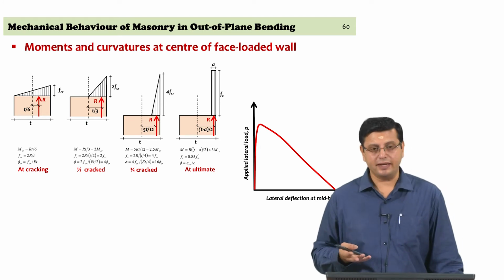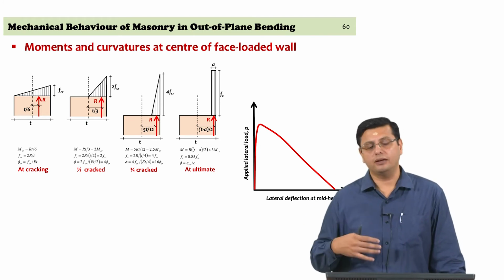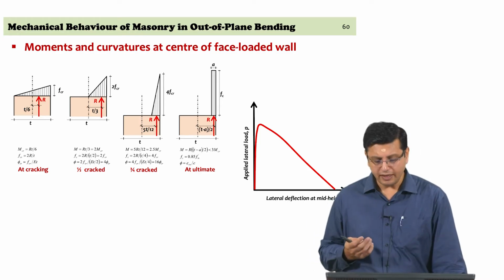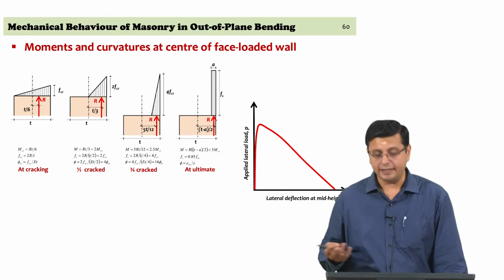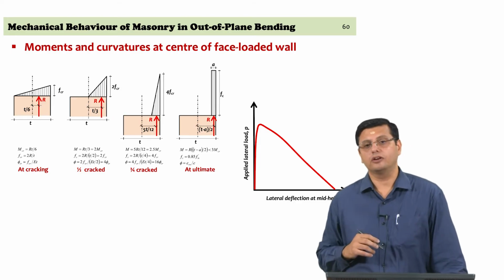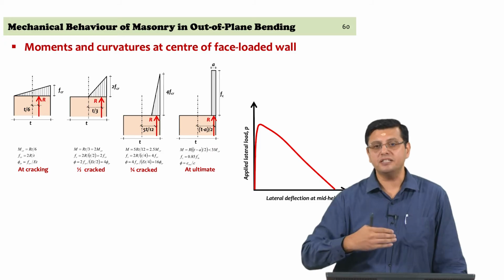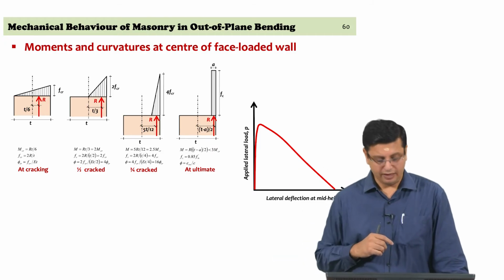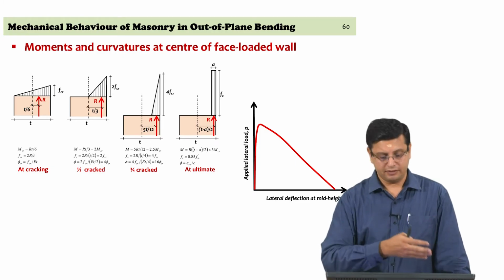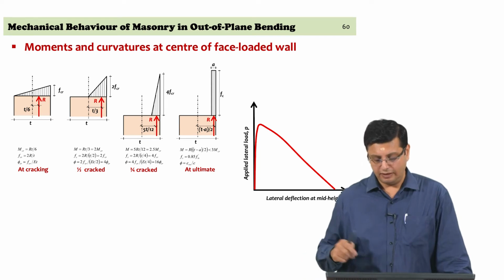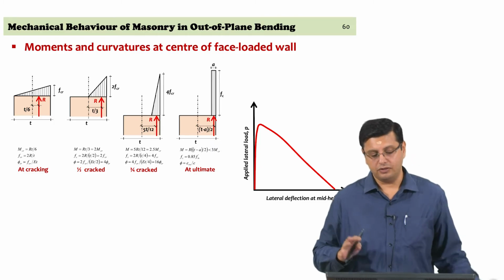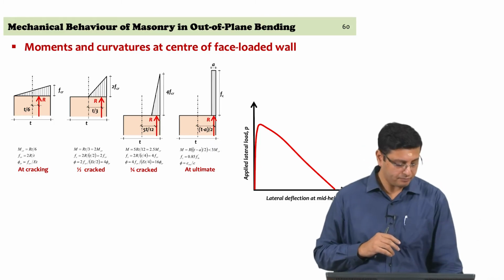In this particular approach, we had looked at a situation where the wall was pin-pinned to begin with. So, if you were to then examine the force displacement relationship, you will get the softening and failure in the system, and the primary difference being close to the peak. When the peak capacity is being reached, you have the softening behavior occurring there, which, compared to the multilinear curve that you saw in the other case, is the fundamental difference that you will get because of the assumption of nonlinearity at ultimate that we are able to bring into the calculations. So, this is what we have seen so far.